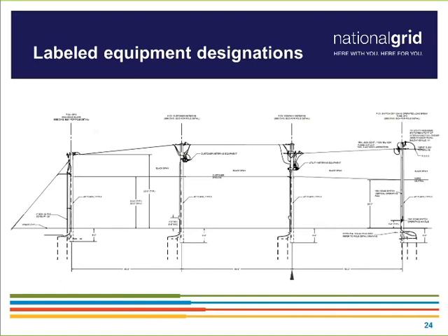So if we have pole customer 1, pole customer 2, pole customer 3, not only is labeling that on the drawing beneficial, but when we go into the field, actually getting those poles labeled in the field provides the ability to make sure everyone has a full, clear understanding as to which point or which device or what piece of equipment is being witness tested or operated.